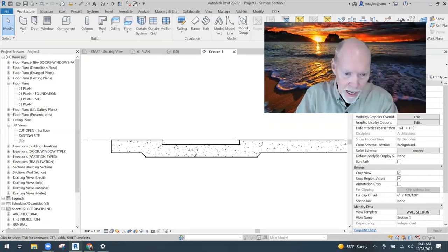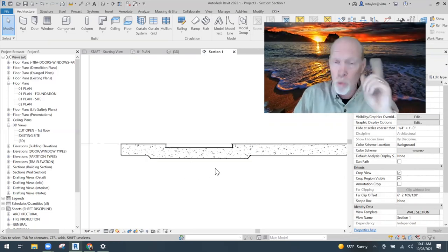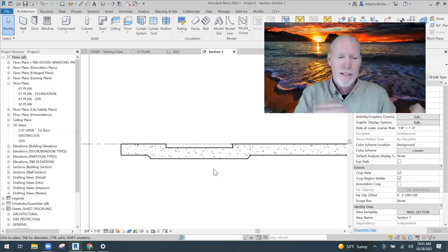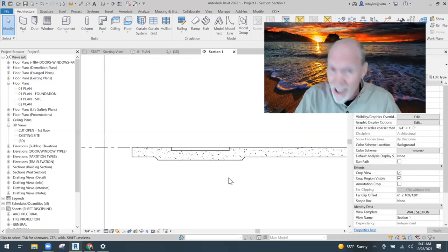So we've got a depressed slab, and it extends 8 inches, and we've got the edges on it. So if I were to change the overlap to a foot, it will track with it perfectly. And so that right there is one way to make a depressed slab, and it's showing properly because it's all true 3D, okay? Now, there's another way, if we had to thicken the slab at the depression.